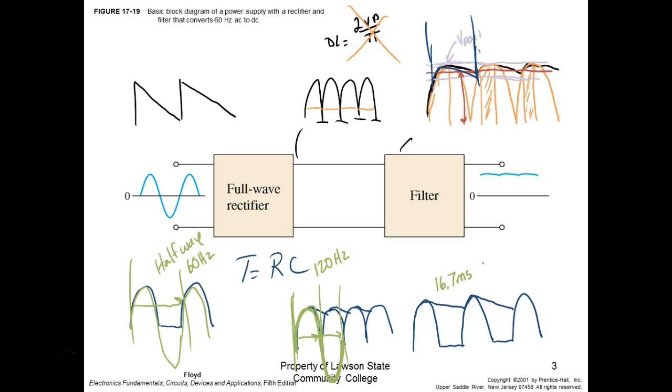Alabama Power gives us 60 hertz. So what did they have to do? How did they change the frequency? Huh? You can't change the frequency with a filter. All a filter does is filter what's there. So they took the AC coming in and used it to run a motor. The motor turned another generator, and that generator gave us 600 hertz. They call them MG sets.